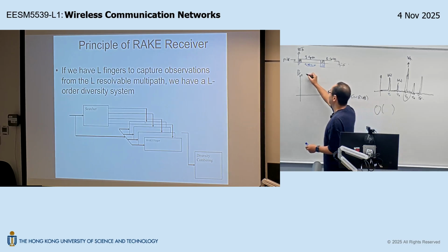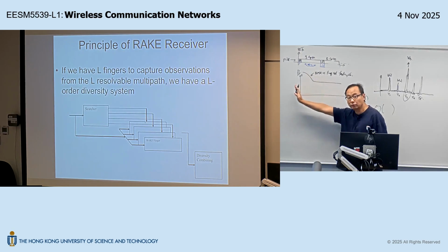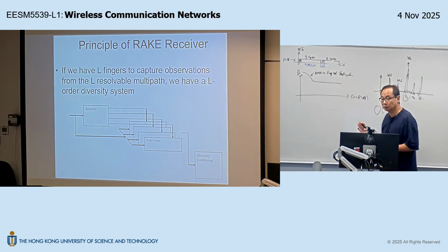We say that if you do not have spread spectrum, let's say just BPSK on a frequency selective fading channel, this is the error curve you have. You have a very slowly decreasing error probability curve in the noise limited region, and you have an irreducible error floor in the interference limited region. So that was the tool we talked about.